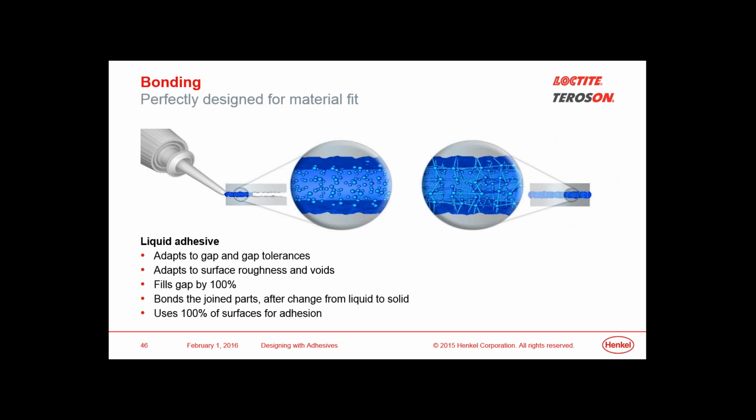One of the advantages of using adhesives, and one of the essential ways that adhesives work, as Mike mentioned earlier, is it's a relationship between wettability and surface energy. If you have the adhesive able to get a good intimate contact with the substrate that it is going to bond, in other words, there are no air bubbles and there are no gaps underneath that liquid, the liquid is in complete contact with the surface to be bonded, that's where you get your optimum bond strength. And of course, most adhesives are liquids, pastes, or something in between. So it's oftentimes the surface energy, not the viscosity, that dominates the performance of adhesion and the wettability of the adhesive.